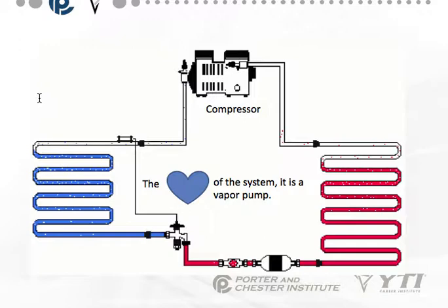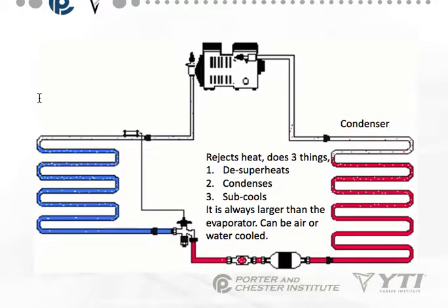The other thing we have to remember is the refrigerant flow through the compressor is what cools the compressor itself. Okay, the oil and the compressor components are all cooled by that flow of refrigerant gas through the system. So that's why it's very important we never run the compressor when there's no refrigerant.